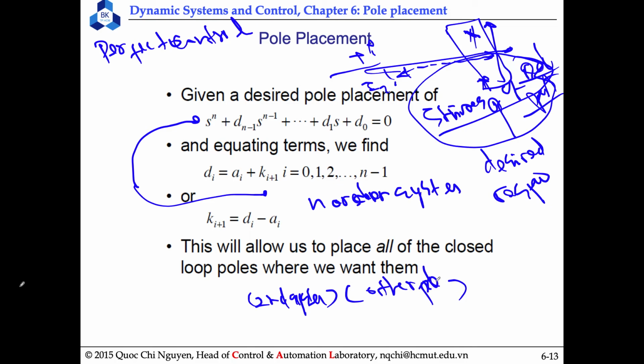But the difference between the feedback control law and the classical control is that these other poles we can also choose, far away from the dominant poles. By combining the two parts like this, we get pole placement, and by combining these two parts, we already have the design.